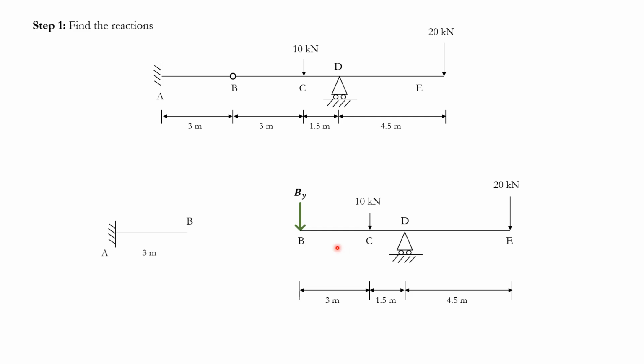And of course, how do we analyze a beam free body diagram? So we remove this roller here, put a reaction here. Again, another arbitrary direction. Good to go. And then we move to the other one. Again, you see this By is going up. Why? Because this By is going down. So if you are drawing this one up, this one should be down. So just keep that in mind. At the end of the day, this point has a net force of 0.